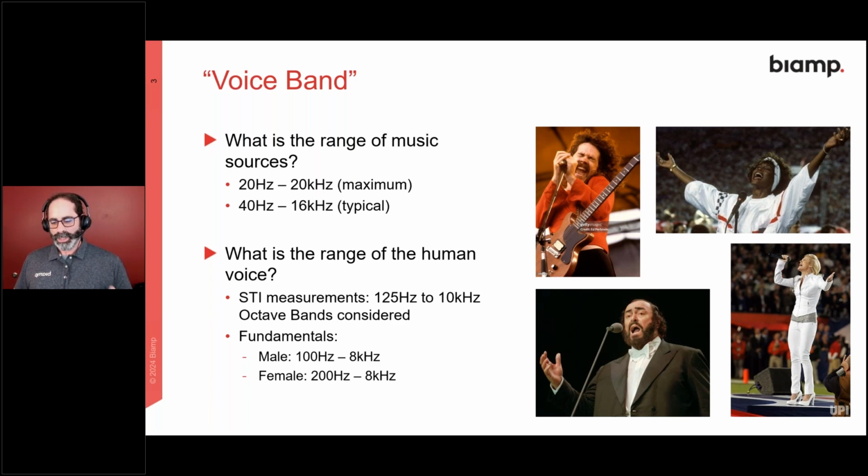I mentioned that because I think one of the things that we just dismiss about paging systems is, as long as we get the middle part of the voice band, it's okay. And technically, to a point, that's true. From about 500 to 4,000 hertz, if you get all those frequencies out to the audience, it's kind of working. But it sounds terrible. It doesn't sound the least bit realistic. It's not pleasant, and it can cause a lot of confusion.